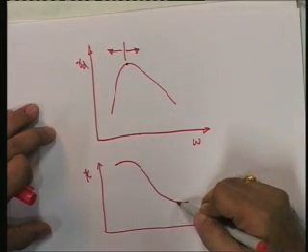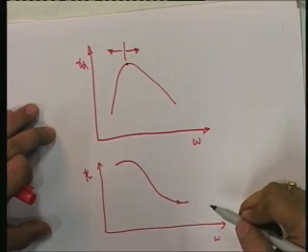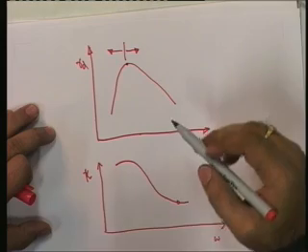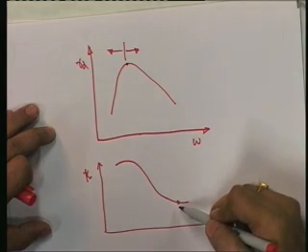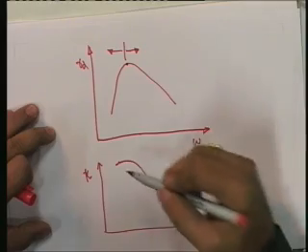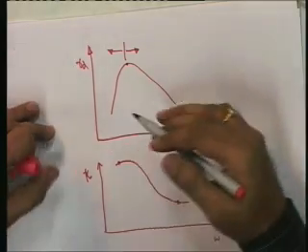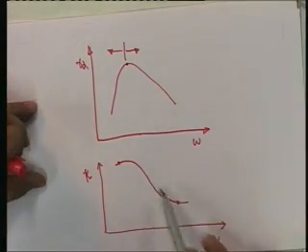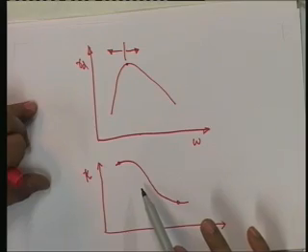So, on the wetter side of the optimum, the coefficient of permeability will be less. On the dry side of optimum, the coefficient of permeability will be high. Thus, this particular region is attributed to the type of the soil structure which is prevailing at that particular moist compacted state or in its natural state.